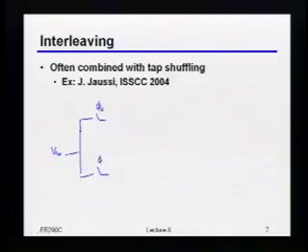So let's say here that that's phi 0 and phi 1, and phi 0 and phi 1 will basically be just clock and clock bar here. Okay, but each one of these will be running at half of the data rate. Okay? So now what I'm going to do is, as I mentioned, instead of just building one filter, I'm going to build two filters, each running at essentially half of the throughput. Okay, so let's say that this was my A0 and A1. Okay? So for this filter, which is running conceptually off of the first clock phase, let's say that I want the data and its first post cursor, right?